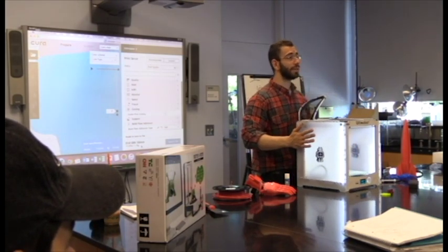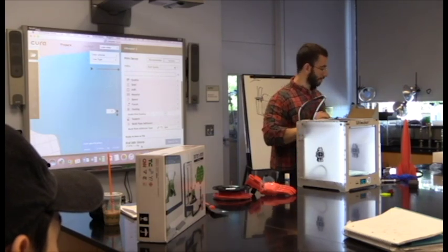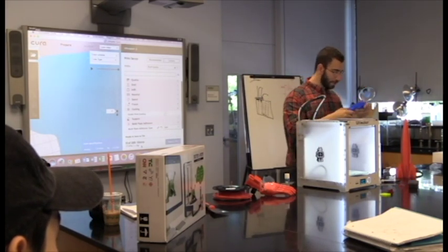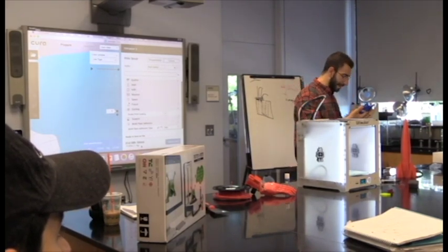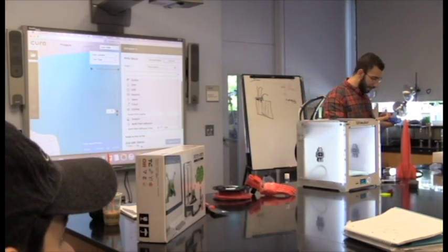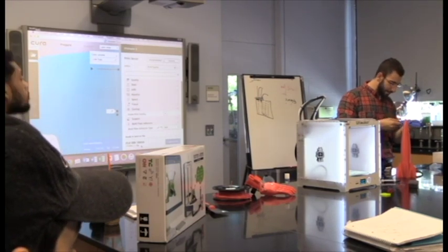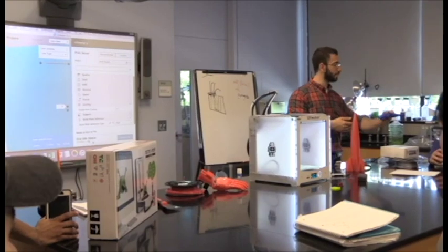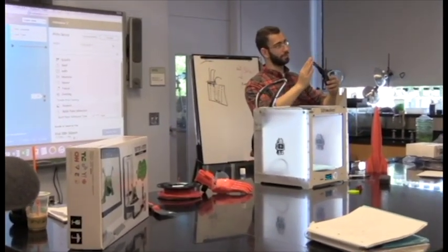Okay, that's how important adhesion to the build plate is. Some of the prints also, like this one, have support in the bottom. You can see the bottom of this hand looks very nasty. The edges look okay, but a lot of it looks nasty because, again, supports leave this look to it. And these, by the way, were printed individually in separate parts.